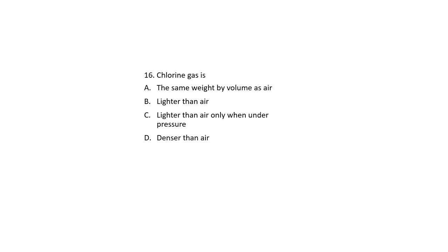Chlorine gas is: same weight by volume as air, lighter than air, higher than air only when under pressure, or D, denser than air. Answer is D. Chlorine gas is 2.5 times heavier than air. Other properties of chlorine gas is a strong odor. It's an easily detectable smell, 0.2 to 0.4 parts per million. It's non-flammable or explosive, but it will support combustion.